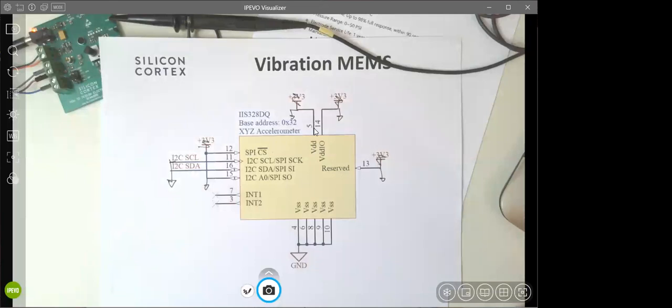That reminds me of a problem. One of the devices that I've had a certain amount to do with is the TI AM3358, I think, as found on a BeagleBone. And one of the things splattered all over the datasheet for that is: do not, under any circumstances, provide power at a non-power pin when the device is otherwise powered down.